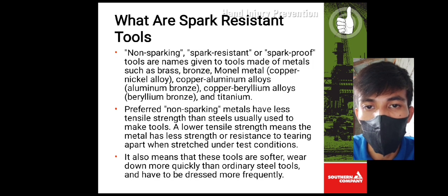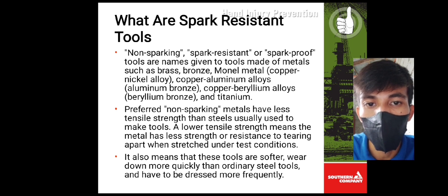What are spark-resistant tools? Non-sparking, spark-resistant, or spark-proof tools are names given to tools made of metal such as brass, bronze, monel metal or copper-nickel alloy, copper aluminum alloys, aluminum bronze, copper beryllium alloys, beryllium bronze, and titanium.